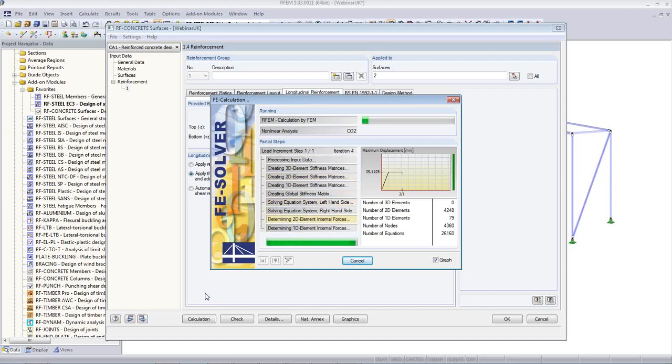The same that you have available for the surface design, we have available also for concrete beam design and concrete column design, everything according to Eurocode, and basically you can do also, as you see here, multi-material structures which consist of steel, concrete, also of timber.